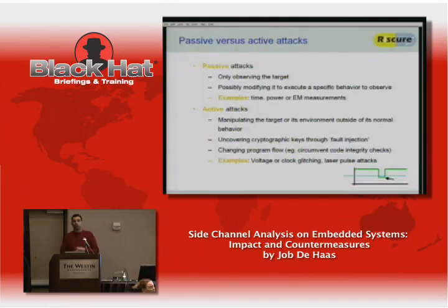So what do you do with them? We distinguish basically 2 types of uses. The first one is passive, and passive is really you measure the signal and then you analyze, but you don't really influence the system. And the other one is active. This morning also there was talk about voltage glitches, optical glitches, the way where you start operating the system outside of its boundaries. Maybe lowering voltages, toying with the clock will induce faults.